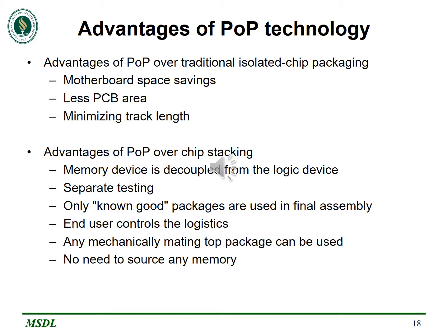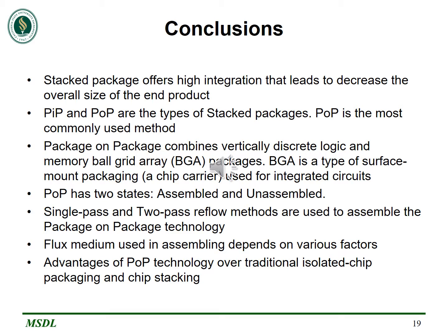For a low-end phone, a smaller memory configuration may be used on the top package instead of a higher-end one. And because the memory only comes into the mix at final assembly, there is no need for logic suppliers to source any memory. With a stacked die device, the logic providers must buy wafers of memory from a memory supplier. To sum it all up, stacked packages offer high integration that leads to a decrease in the overall size of the end product. Package in package and package on package are the types of stacked packages used in industries nowadays.